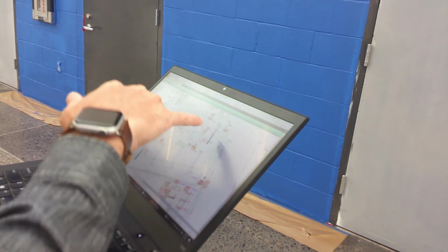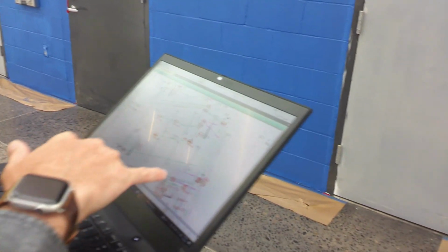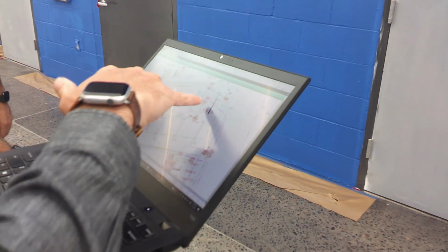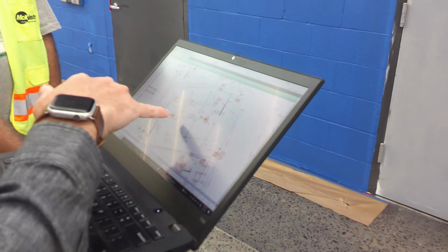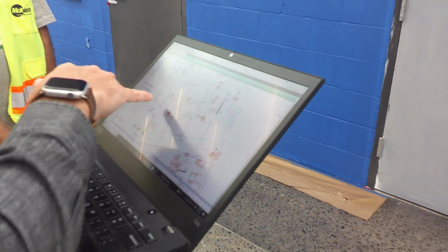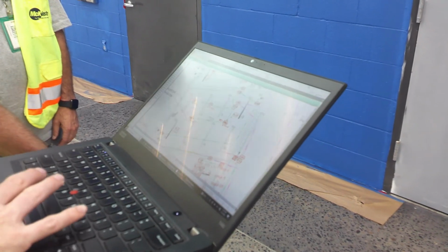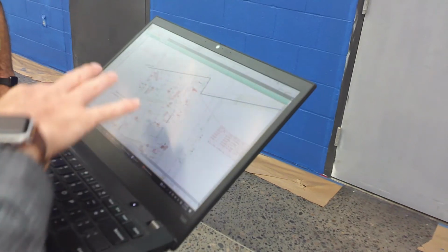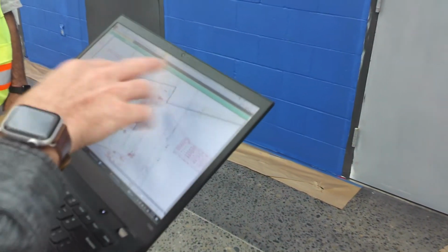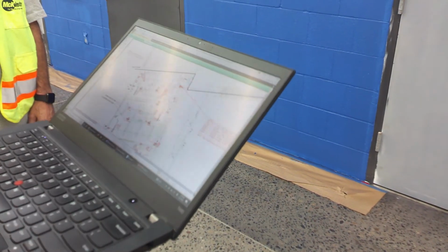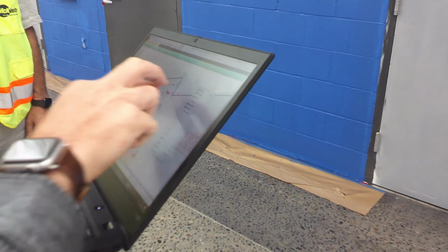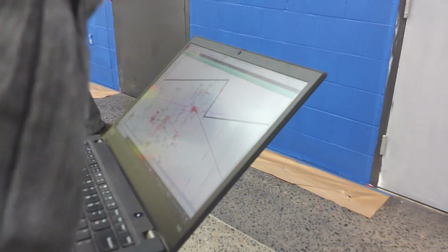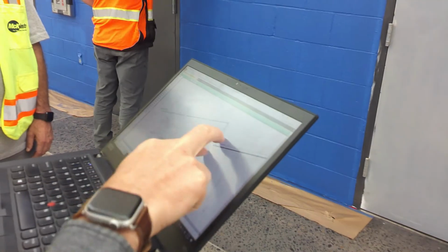In a classroom, for example, you've got the bridge, which is chaining on the network, then going down to the 3 controllers. Controllers are connected to the sensors and the switches and the photocell there. So this is the controls design for the whole building, a helpful reference to have. There is the indication of the PoE switch. It's actually in that MDF over there, so we'll go check that out.